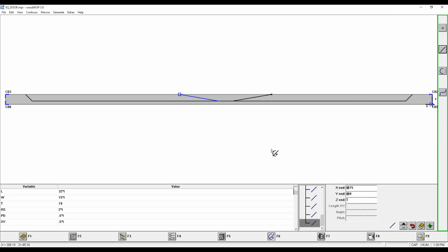That's my raised panel door. So if we want to put a flat tool on there, I just create a rectangle in the middle so that my flat tool can cut. I don't need the corner moves for that. And then I could possibly use that same inside shape without the corners to put a profiling tool. So I would have a raised panel bit. My order of operations, I would do the flat tool, then I would do the V point, and then I would do the raised panel. That way I'm not running the risk of having the tools overcut each other.